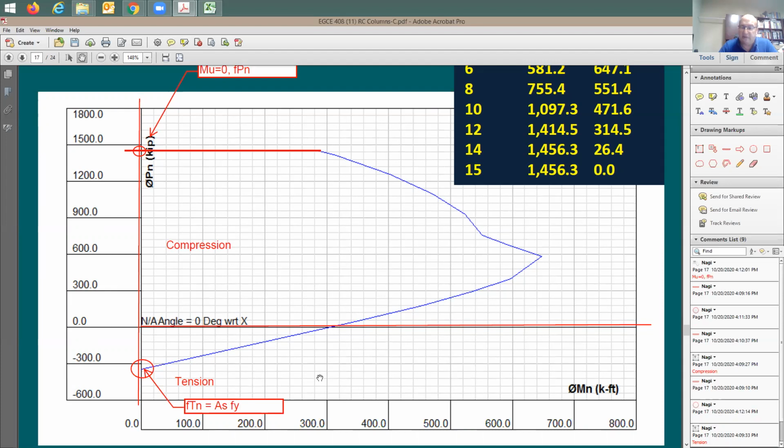So I was going to say, how about the concrete? I'm going to say this is here an axial tension. There is no moment at all, and there is no compression on the section. The entire concrete section is going to be cracked, and therefore the only tension component is going to be the steel rebars. So if you have the total cross-section area of all the vertical reinforcing bars multiplied by F sub y, it's going to give you your Tn, and then of course you need to multiply it here by phi, and phi in this case is going to be equal to 0.9.